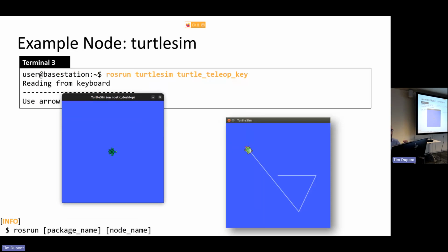Well, yeah, for this example, yes. So this will just start by typing. But if you create a ROS system, you create a specific file called ROS launch, and that will start multiple nodes that you need, or other systems, or other ways to start processes, and then you will start all nodes automatically. That's for today, all in one container. So it's really making your hands dirty and takes a lot of time, but it's a good introduction.